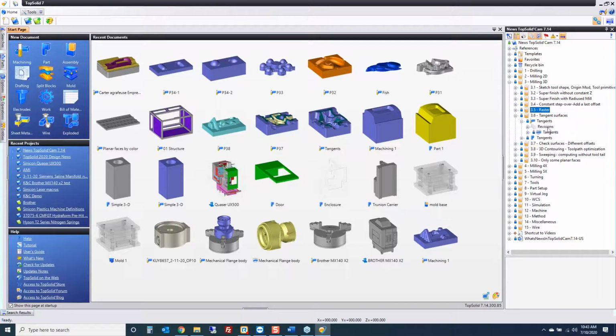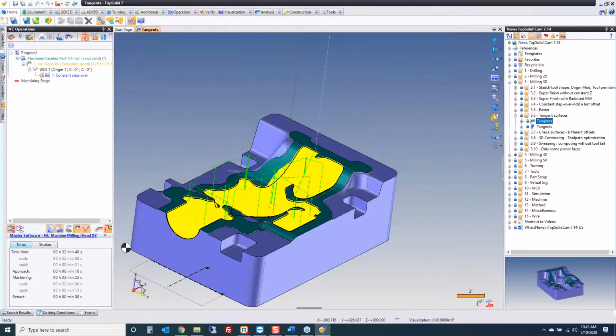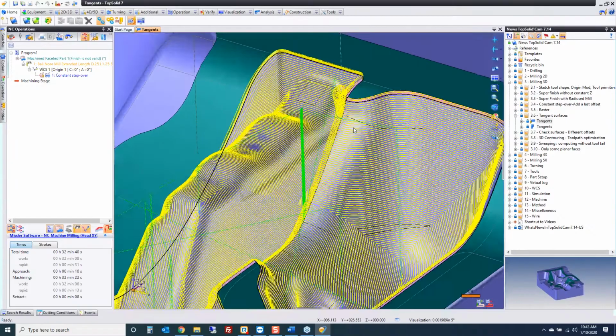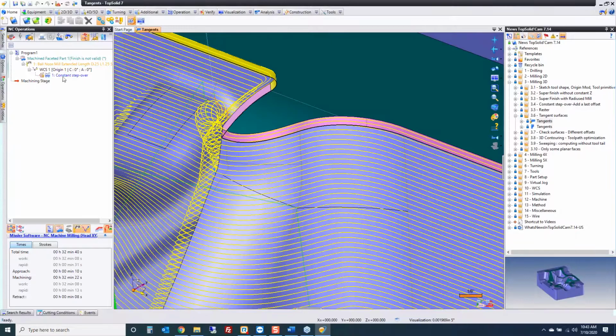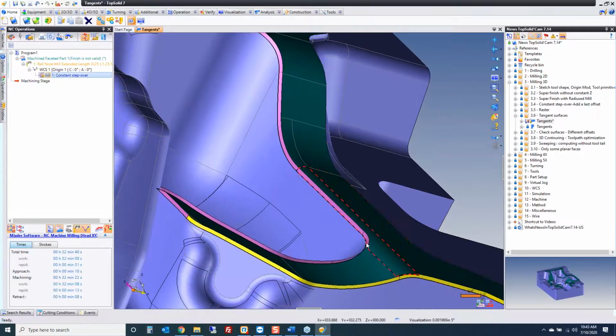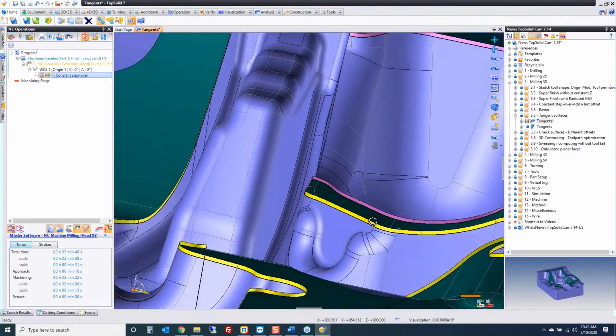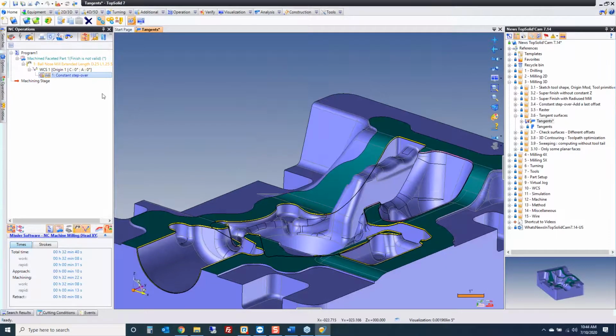All right, this next one should have everyone giddy. This one will take some time to go over because there's a few steps involved in it, but I want to talk about what it is first. So again, one of the goals was to give you tools to help you maintain sharp edges on your 3D toolpath. If I zoom up on this thing, you can see my toolpath is coming up and following some additional surfaces, right? If I turn off my toolpath so you can see the additional surfaces, I have created surfaces all the way around that appear to be tangent. That's kind of awesome.